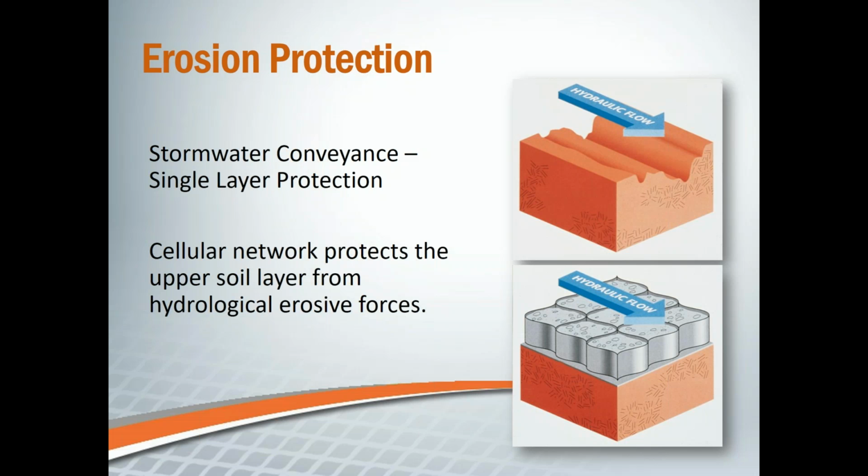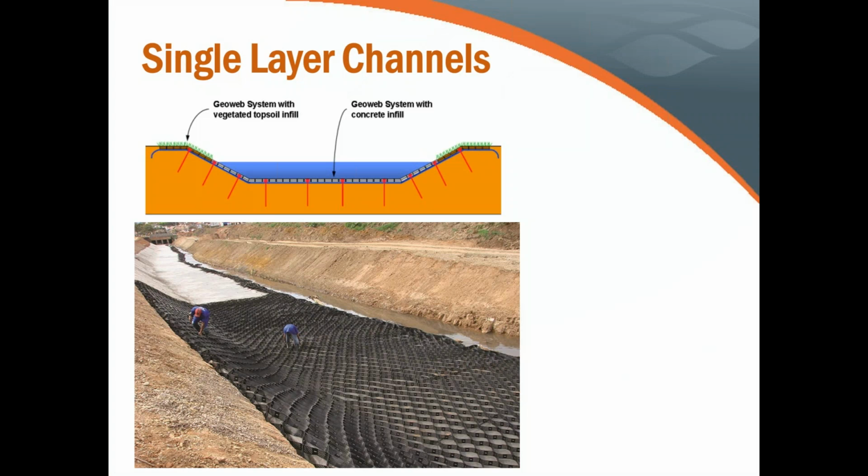Using the 3D is much more effective. Each flexible cell is protected against erosive force, whereas 2D solutions such as erosion control blankets, ECBs, only protect the channel from hydraulic forces of the water, and so the channel may fail, even if the 2D solution is still in place.